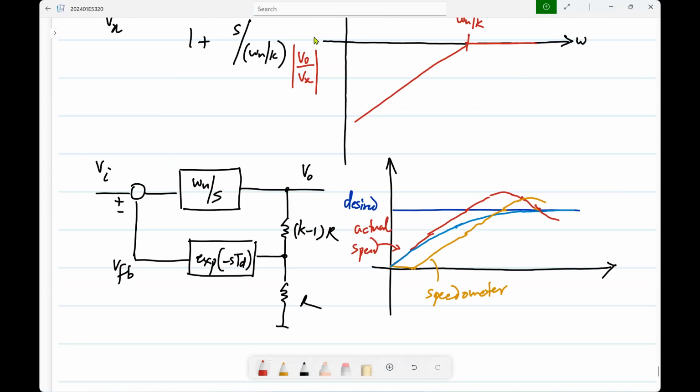So then what you can do without changing anything else is that you simply accelerate more gently so that over the delay offered by that speedometer, you don't change the speed all that much. Then even if you overshoot, you will overshoot only by a little bit, or you may not overshoot. We'll see. Is this okay?